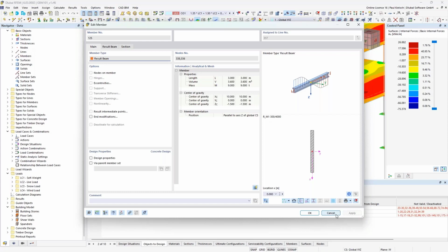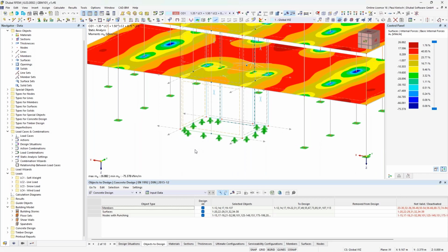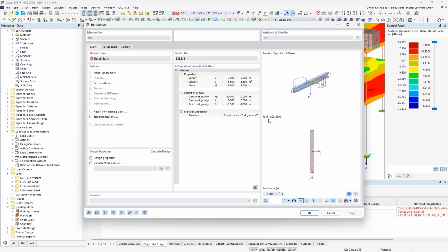Of course, you may be asking yourself, why haven't we selected also the combination of this wall, and this wall? So maybe you would expect a shear wall with a member with a section of C shape or L shape, like I would have selected just these two surfaces. That will be possible in the future. But in this case, if you would assign, let's say, these three walls, the program would generate a section with a C shape, and then it would not be a rectangle section, like in this case, but it would be a C shape R section.